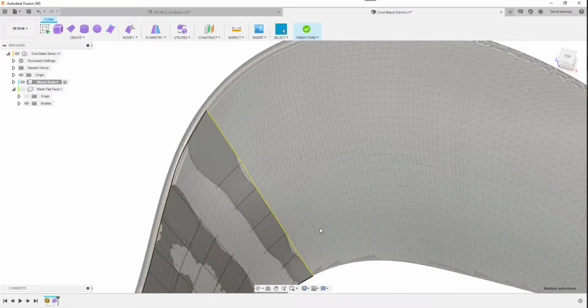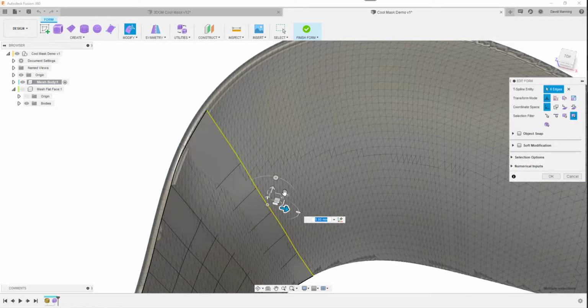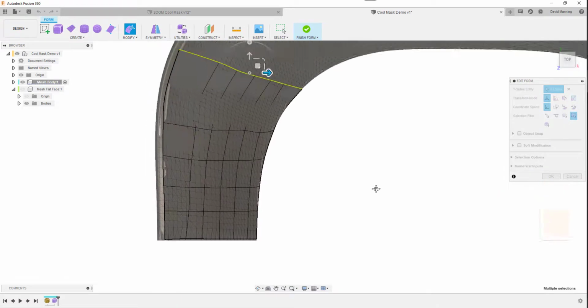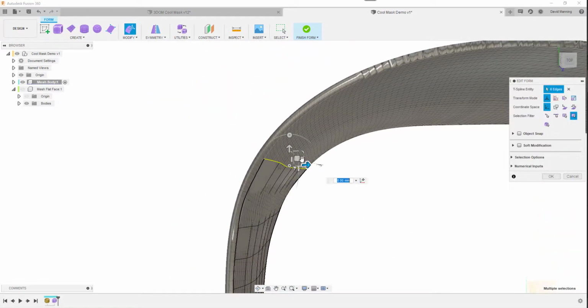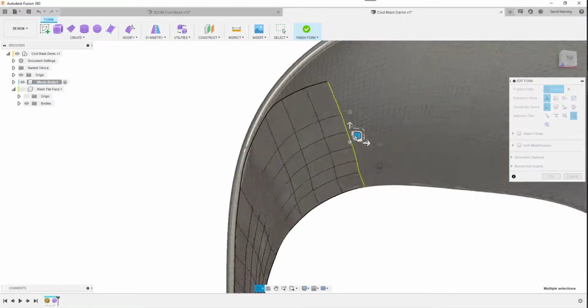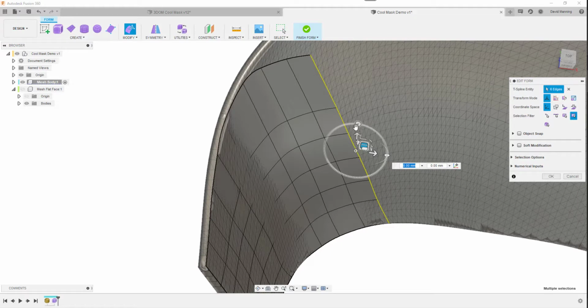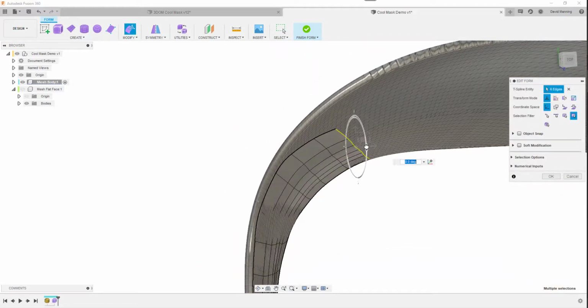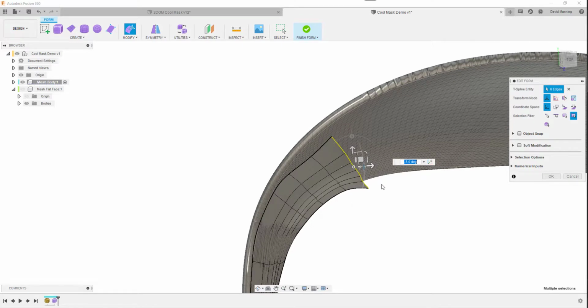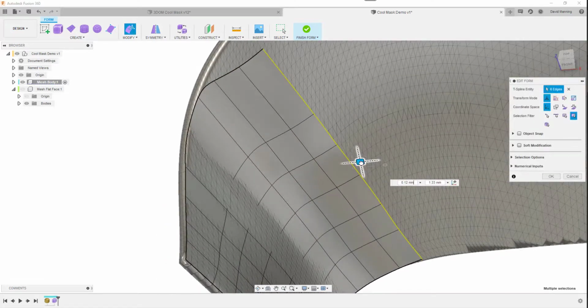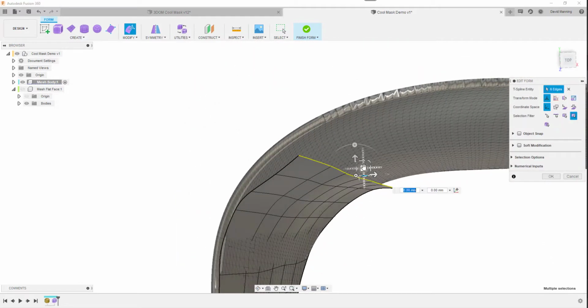meshes manually like we did to start with, or one of the cool things is, like I said, using the Alt tool. If I go to the top view, rotate it around a little bit, I can hold Alt and add vertices in there just as easily, and as I add each one, it highlights that. Now I've selected that whole line, so it's adding them to there. I can do things like change the angle of that. I can physically move that up, and I can continue adding to that mesh using that Alt if I want to.